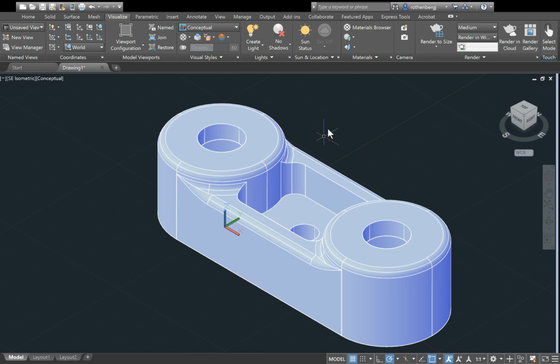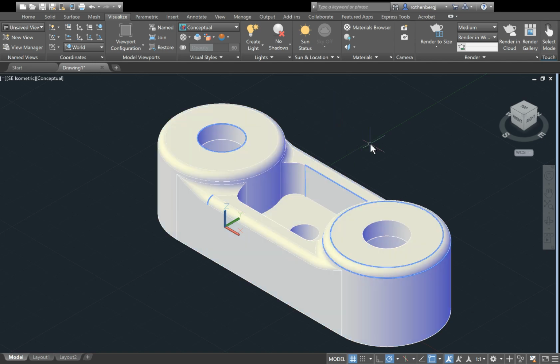So next we have to do just a few more edges and then we'll be done. As you can see, it has selected some random edges on here for some reason. You don't actually have to worry about that. That's just a weird CAD thing. But if you don't like it for whatever reason, just select them, select the whole object, then hit escape and they'll go away.